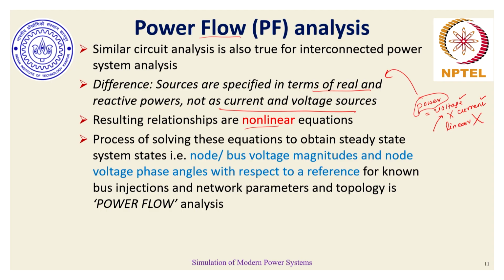The first module that we will talk about, which is power flow analysis, will essentially help us understand how to solve these nonlinear equations for a given interconnected power network, where the bus or node injections, or powers, are known, at least for some buses and some nodes. The network parameters are known, that means the line resistances, inductances, and capacitances are known.